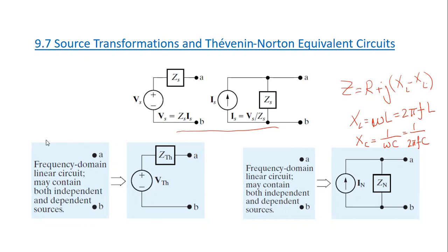And here we have a Thevenin and Norton equivalent at the end of this slide. So as you remember, in Thevenin equivalent, any given linear circuit can be converted into a voltage source, which is equal to V Thevenin, or V open circuit between these 2 points, A and B, in series with the Z Thevenin. And let me remind you how to find V Thevenin. V Thevenin can be found by calculating the voltage between A and B. So it's the open circuit voltage between these 2 points.